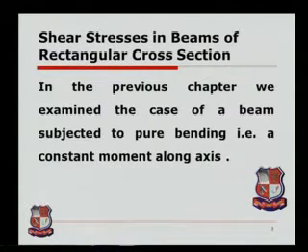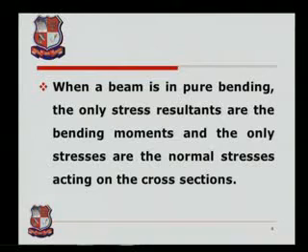So in the previous chapter we examined the case of a beam that is subjected to pure bending, that is a constant moment along the axis. When a beam is in pure bending, the only stress resultants are the bending moments, and the only stresses are the normal stresses acting on the cross section. So we all know that whenever a beam is subjected to transverse load, then there is development of shear force as well as bending moments. The bending moments are responsible for the bending stresses, whereas the shear forces are responsible for the shear stresses.